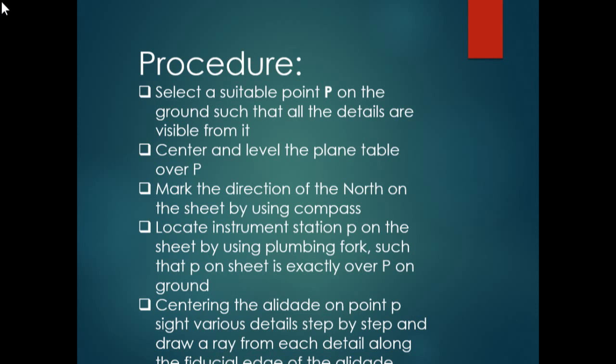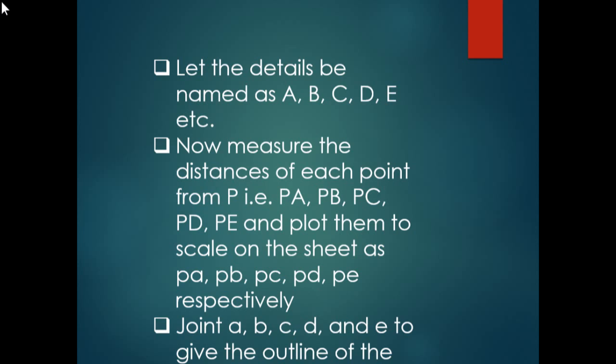Centering the alidade on point P, sight various details step by step, and draw a ray to each detail along the fiducial edge of the alidade.